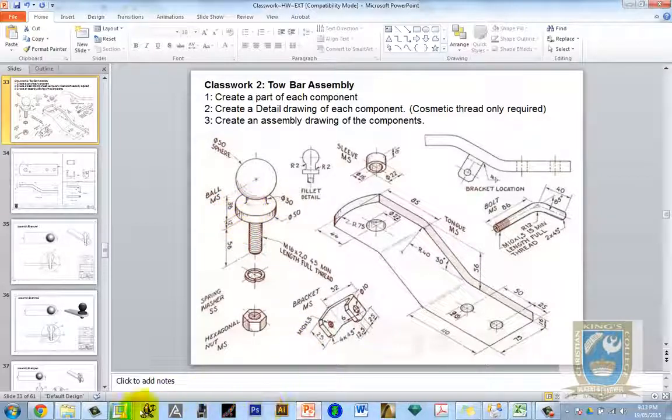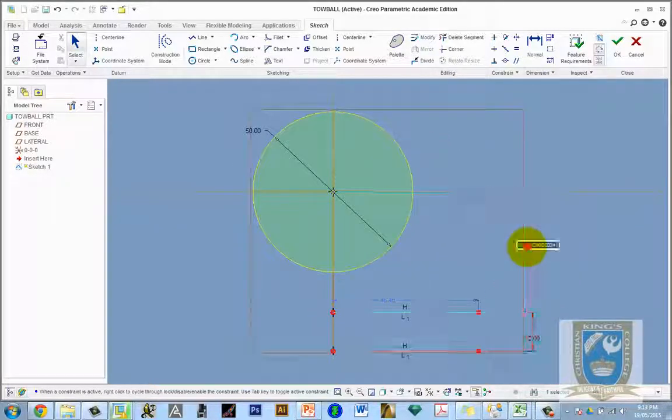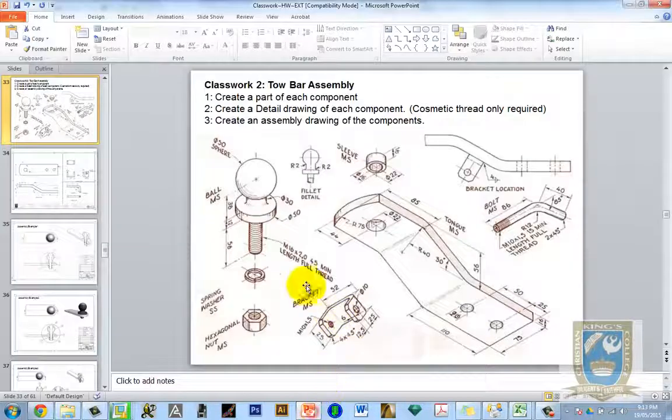So what I might do is go to Creo and just using my line tool somewhere down here, I don't really know where exactly yet, I'm going to draw 2 lines in, and then I'm going to dimension those appropriately. So I'll pull these dimensions out, 1 and 2, so that was 12, I think, between those two, and I think that was 38. I think, gee, that was close. 38 and 12. Let's go back and check. 38 and 12. Wow, that was close.